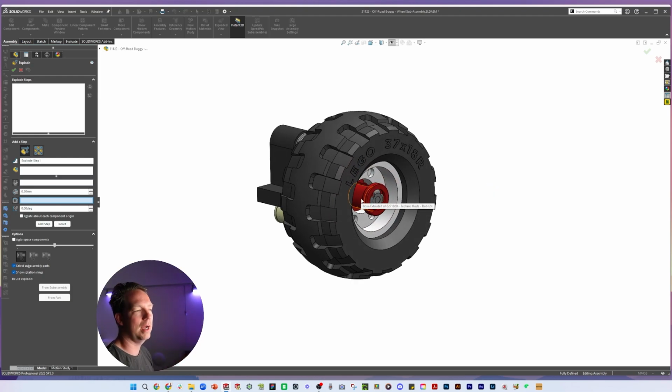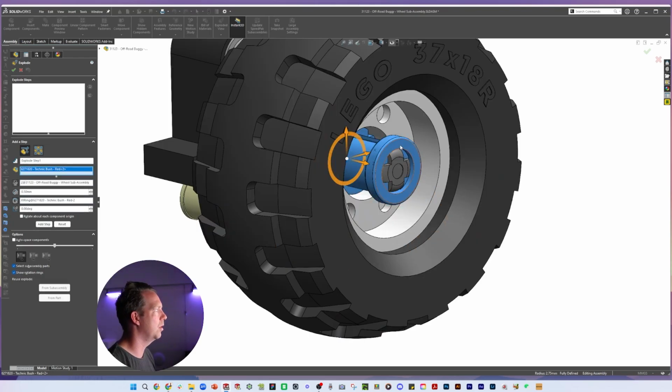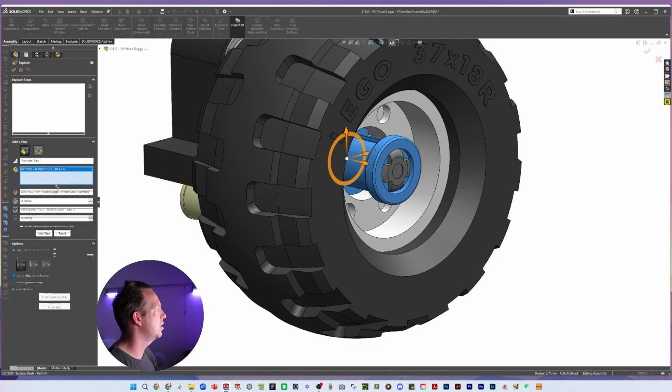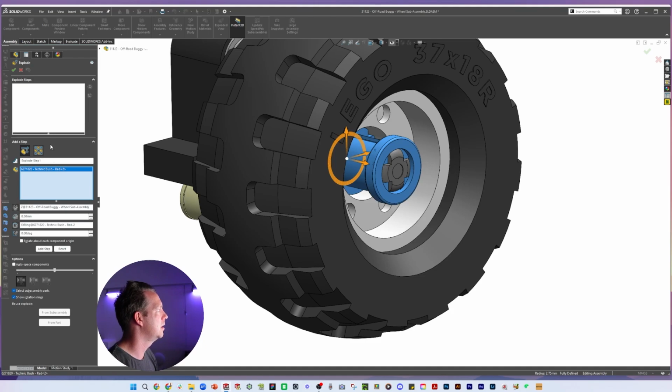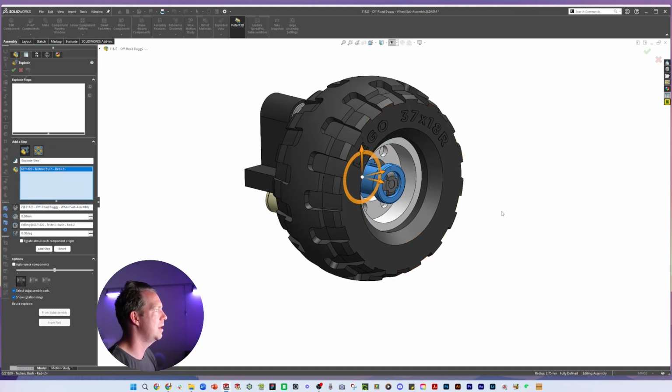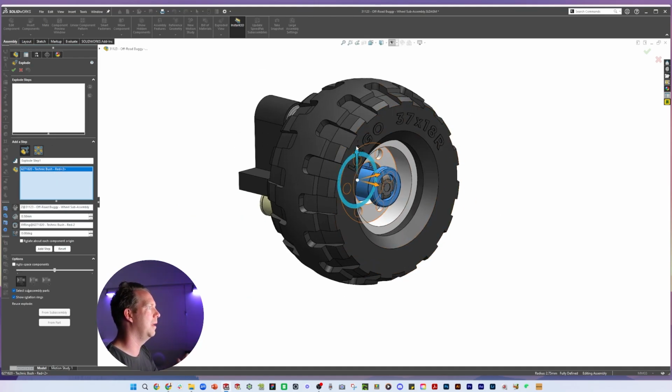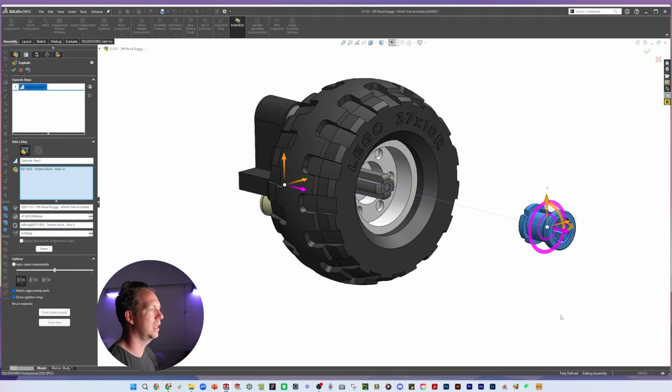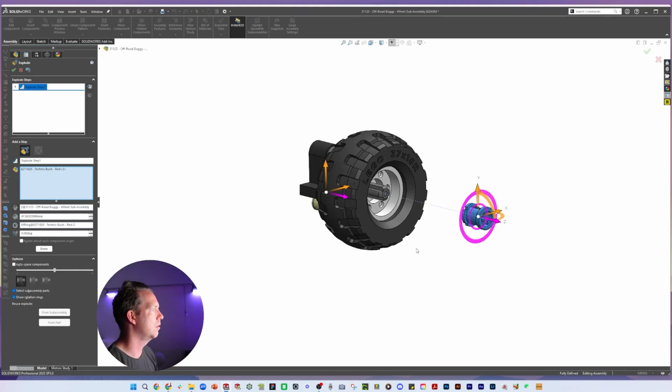I'm going to click one part. I'm going to click this red one, and it didn't work. I'm just going to make sure that the body I'm selecting here is this blue box on the left, and then I'm going to click that body, and now you can see the whole body is highlighted blue, and it's come up here in the feature tree, and it's identified that as the part. Okay, if I just drag that down, you can see that's the one. And then you can see the axis is the arrows here. And the round section lets you do a rotation. We're not going to do that. In this case, all I want to do is click and drag this out like that. Done. Very easy.